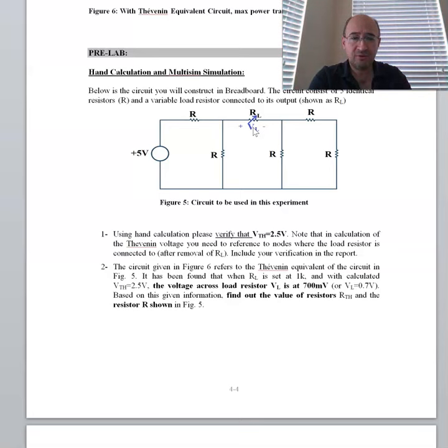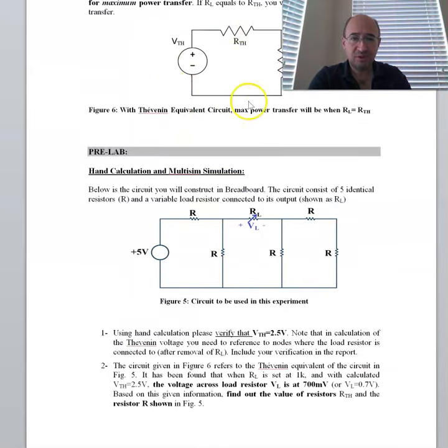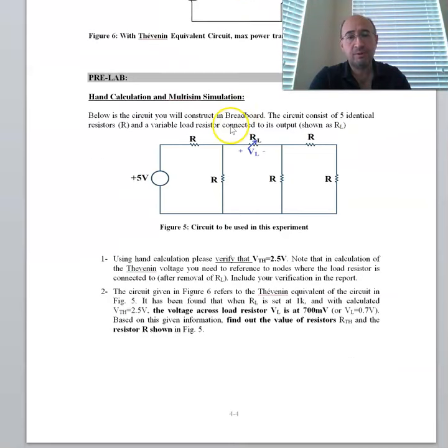So you can refer to the voltage division circuit or the Thevenin equivalent circuit to figure out the value of RThevenin, because you know the load value and the load voltage, and you know what VTH is, so you can easily figure the value of RTH. Now, referring to figure 5, you should be able to formulate RThevenin as well.